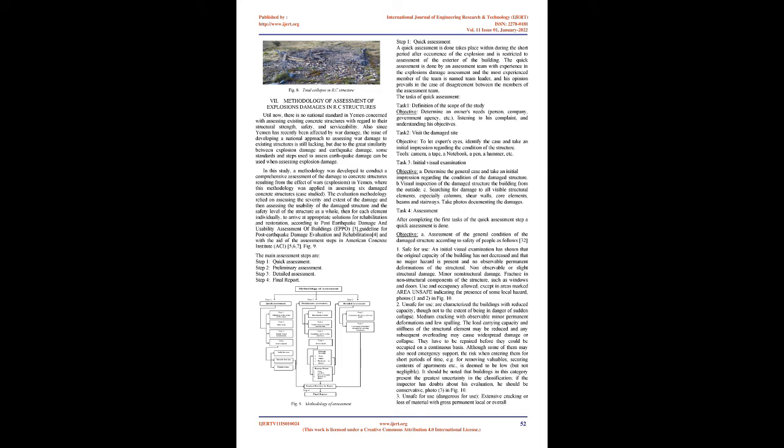Step 1, Quick Assessment. A quick assessment takes place during the short period after the occurrence of the explosion and is restricted to assessment of the exterior of the building. The quick assessment is done by an assessment team with experience in explosion damage assessment, and the most experienced member of the team is named team leader, and his opinion prevails in case of disagreement between the members of the assessment team. The tasks of quick assessment.